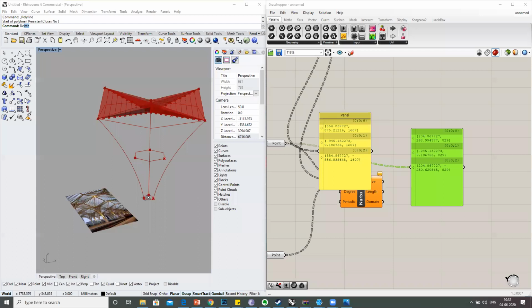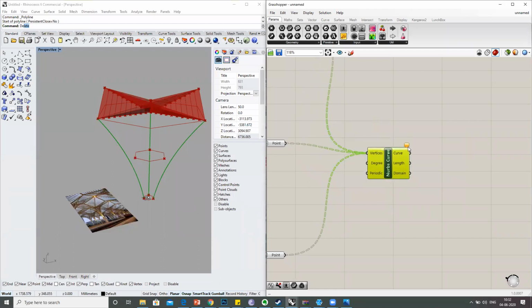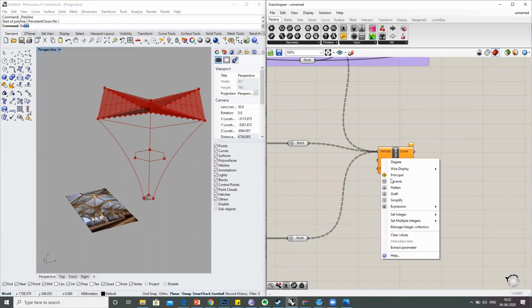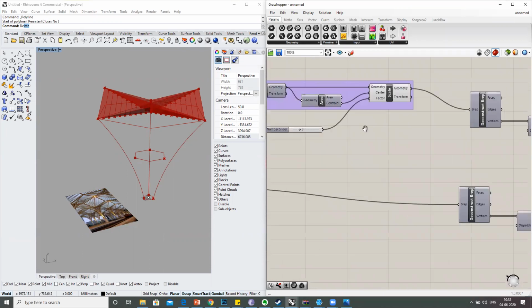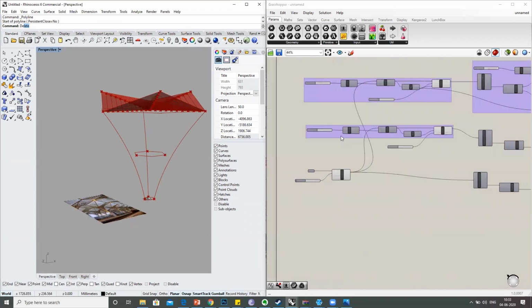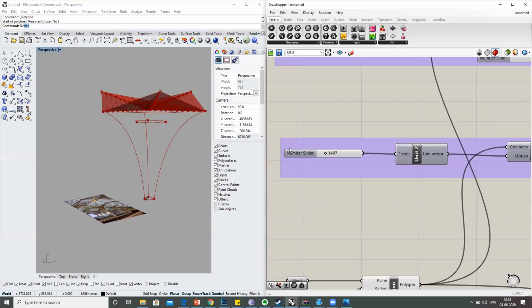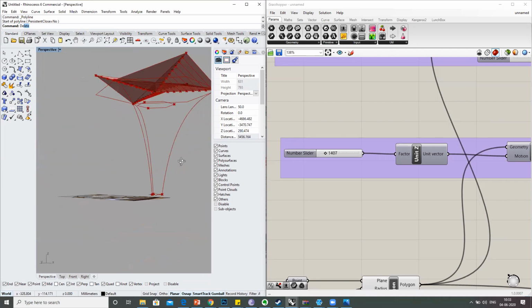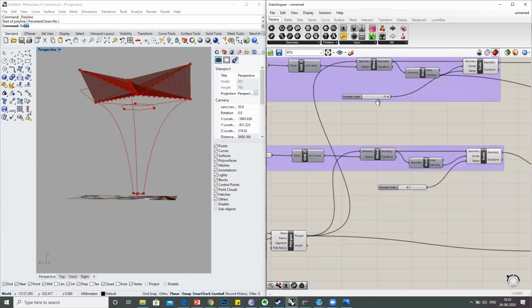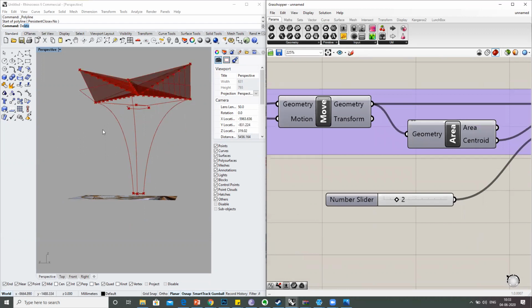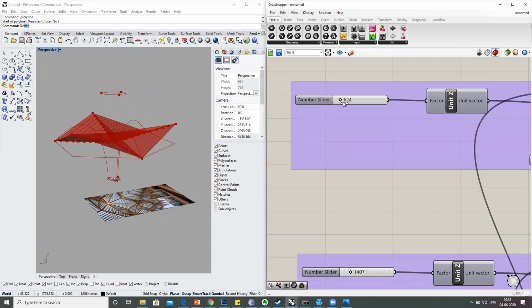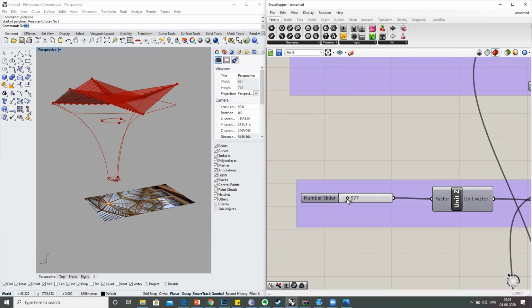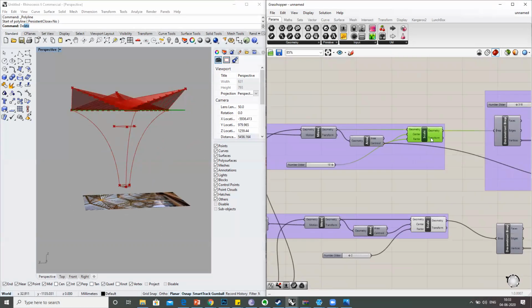So well and good, we've got our curves. The degree must be lesser than the number of control points. It's not a big issue, but you can change it or you can drop it and it shouldn't be a problem. Now, if you see, I've got all these curves, and now if I play along with these values, I can play with the form factor. I can play with the factor. I can play with the height. There you go. Now I don't want this hexagon, so I can hide it.